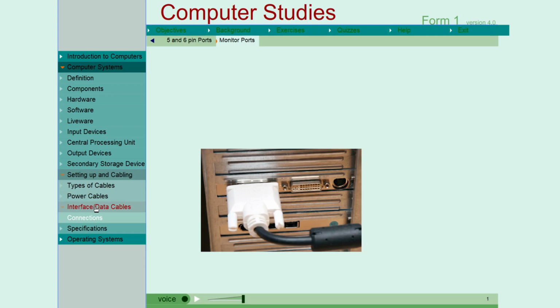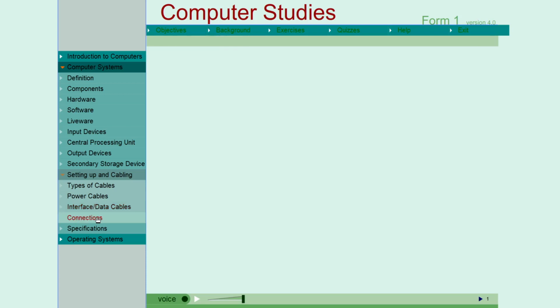The following rules should be observed before you carry out setup activity. Disconnect all devices from power. Discharge static electricity that might have built up on the hands by touching an earthed metallic object or wearing an anti-static wrist strap.